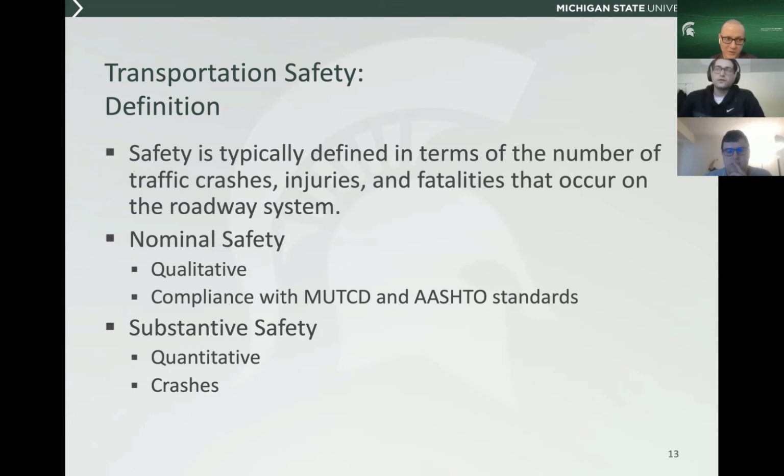And as a remedial measure, you could look at things like reducing speeds, introducing advisory speeds on horizontal curves, as one example there. And so we're looking at both of these aspects, but design has become much more data driven now than it was particularly 30 years ago, but even 10 years ago. So oftentimes now, instead of just designing a roadway where you're working through the Green Book and making sure that you're at or above those minimums, it's more of a quantitative process. So there is some granularity here, and there's also some degree of limitation.